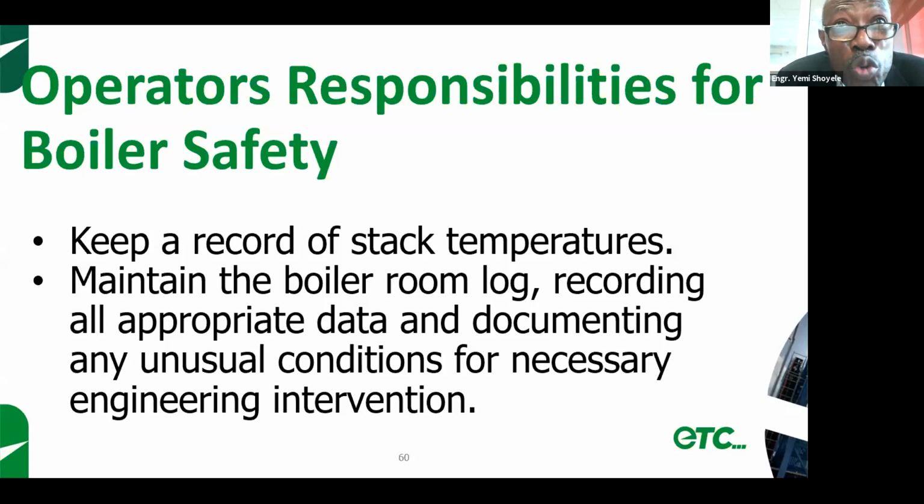I recommend between 92 and 95 degrees centigrade for the water tube boilers. That is the main thing. But you must also ensure that your firing rate, the adjustment of your burners, is okay. Nobody has done anything after a weekend maintenance or whatever. Somebody did not adjust something very well. Ensure that is okay. Once that is okay, make sure that you have your feed water temperature as close as possible to 95. Then there will be no problem.